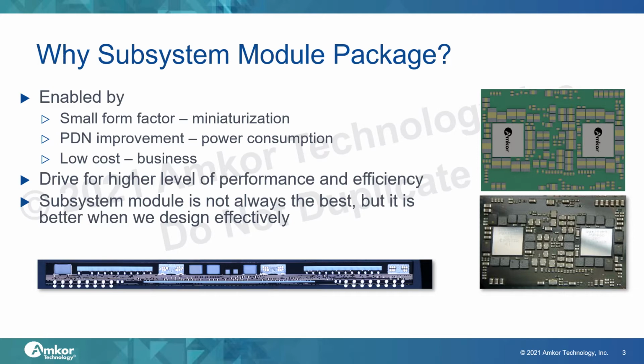Subsystem module can integrate a single function with multi-chips and components into a single package, and it can provide a shorter power decoupling path and small form factors. We can take advantage of three major topics today. First, small form factor. Second, power distribution network improvement. Third, of course, low cost.